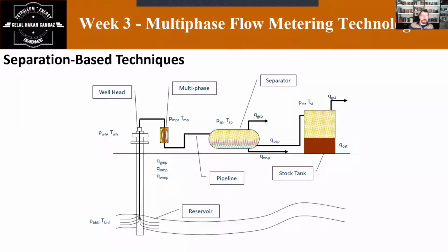Actually, after a while, it becomes that oil. Some part of the gas which was included inside the oil as a solution has gone out as well, as I mentioned in the second week. And what happens? Your stock tank oil becomes available after 12 hours at least. Okay, and you separate another part of your gas in here too. So of course, all these steps will have different phase diagrams.